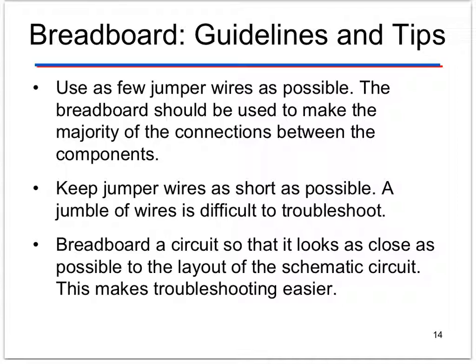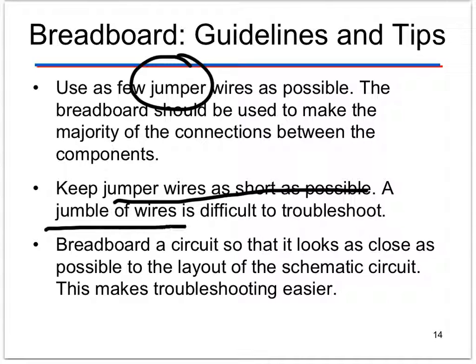And breadboarding is definitely a skill. We're going to build a circuit midway through the course that is going to require a ton of wires. And if you don't practice using good breadboarding skills, it's just going to make it extremely difficult. So you want to use as few wires as possible and few jumper wires. And a jumper wire connects one hole to another. You need to keep wires as short as possible. Don't create a jumble of wires that's basically a bird nest.